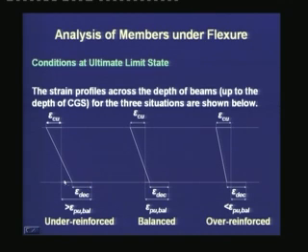The total strain in the prestressing tendon is equal to the strain in the concrete at the level of the steel plus epsilon DEC, and for an under reinforced section it should be greater than epsilon PU balance. On the other hand, if we look at the right diagram, there the strain in the steel will be lower than epsilon PU balance when the extreme compressive strain in the concrete is epsilon Cu, whereas the transition we are saying that it is a balanced condition where the strain in the prestressing steel is equal to epsilon PU balance.